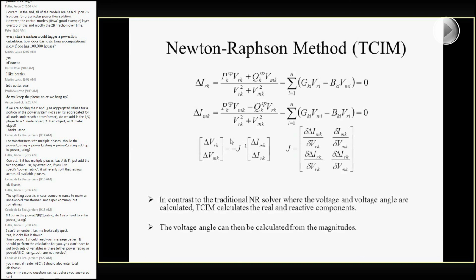Obviously, it's a trade-off. The forward-backward sweep one will iterate a lot more, but it's a much simpler power flow, so it iterates faster. So you'll have more iterations, but quicker time, whereas the Newton-Raphson will require fewer iterations, but there's this great big matrix inversion in the middle, which eats up some computational cycles, so fewer iterations, but slower. I don't know what the break-even point is.